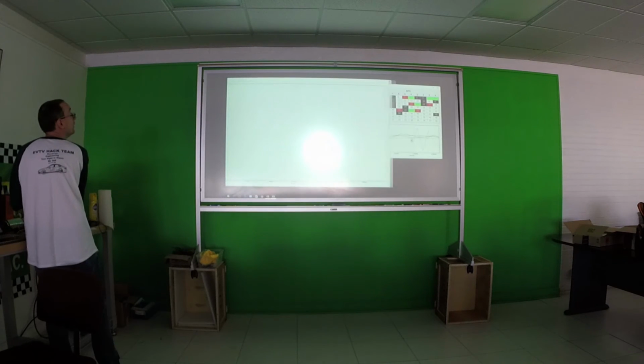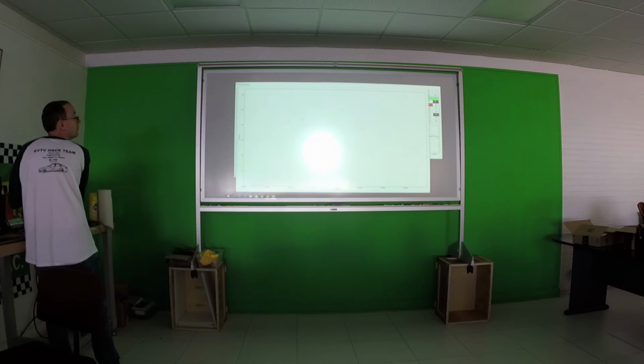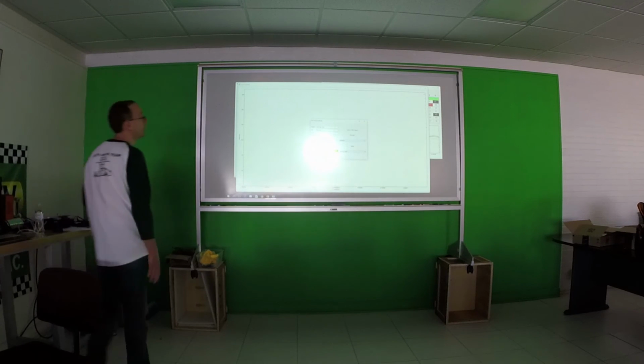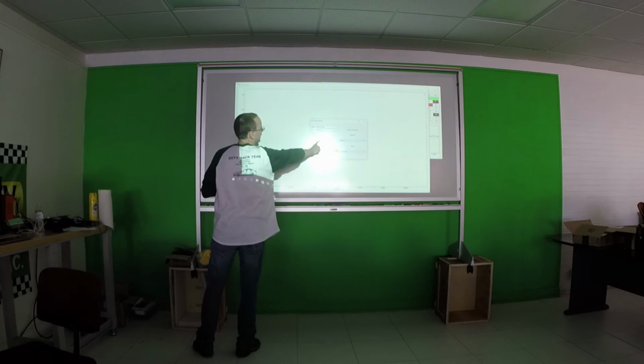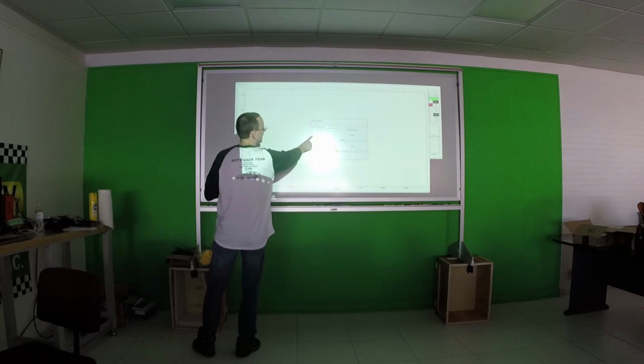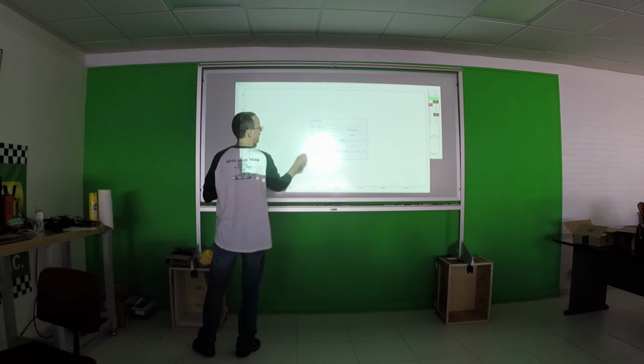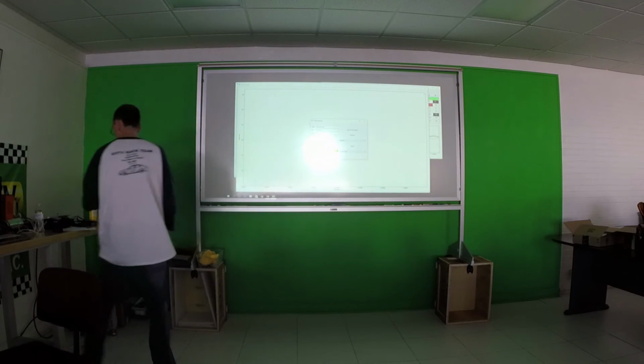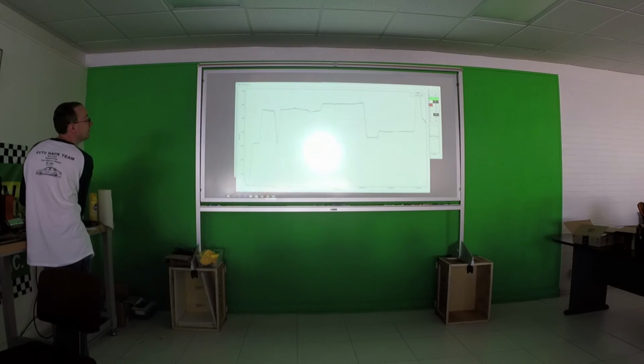Now on to the graphing window. You right-click on this, say Add New Graph. The power of a DBC file is I can select things from the DBC file that I want to graph. Let's say I want to graph motor RPMs, and it fills all this in for you. Ordinarily, the RPM is found in ID 0 or 106. It's found in bytes 5 and 4, with 5 being the high byte and 4 being the low byte. It is signed, and remember I said it was a 14-bit value, so the mask here masks off the top 2 bits so they don't interfere with us. The scale and bias are all pretty standard. The RPM is stored that way.